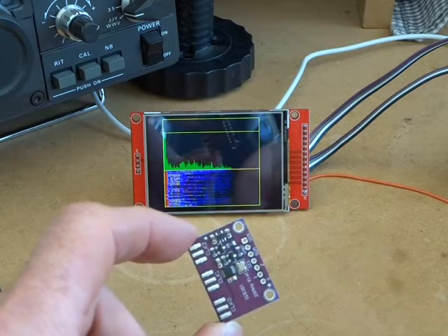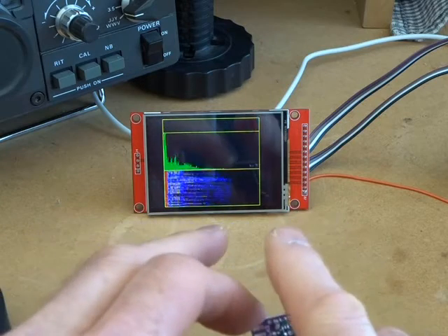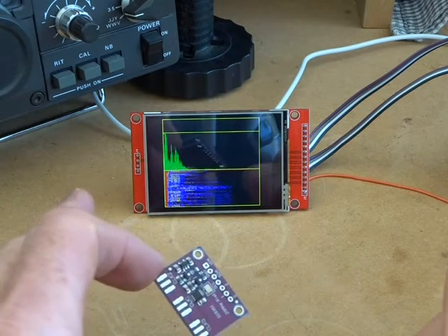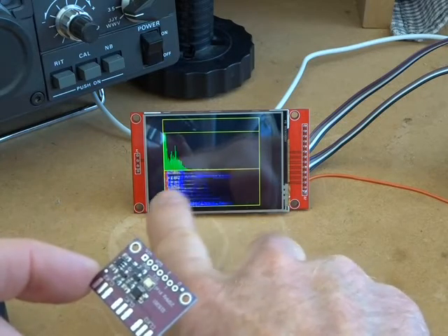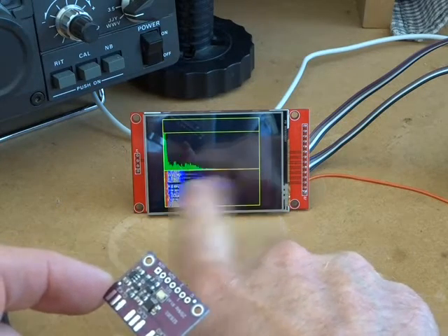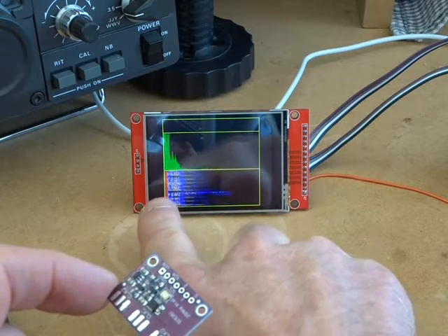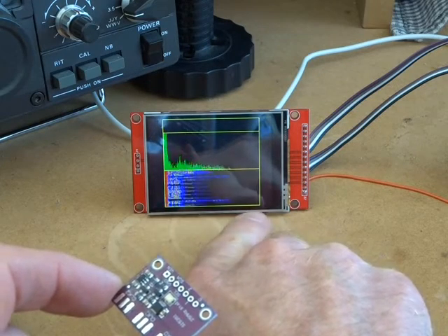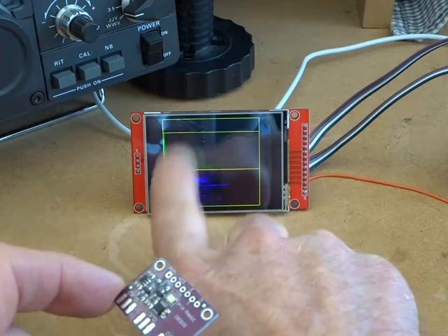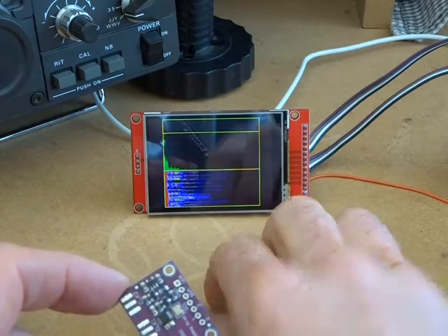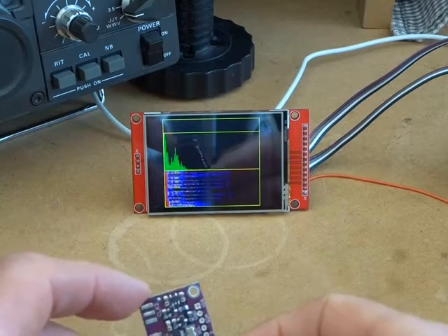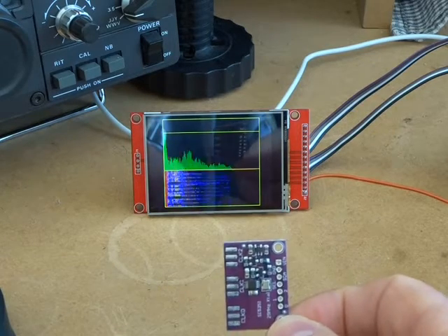The restrictions being, each ham band is quite wide, a good 200 or 300 kilohertz wide, but I've only got a screen bandwidth there of 20 kilohertz. So it's how much we want to try and display of that band on the screen, which then is a function of resolution as well. So some compromises there that need to be thought about before moving forward.